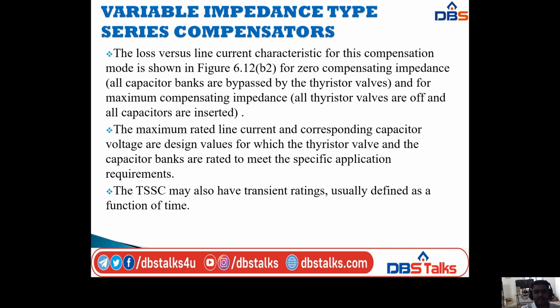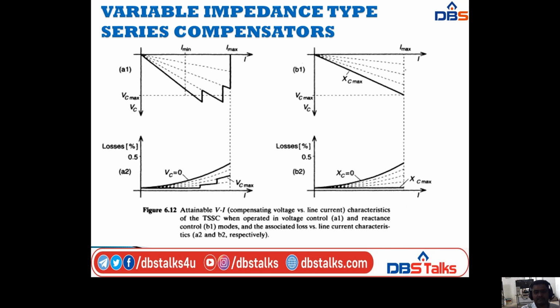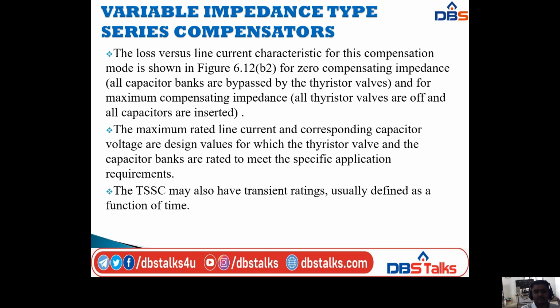Next I am discussing the last diagram of the VA characteristics and losses versus line current characteristics, that is B2. The loss versus line current characteristics for this compensation mode is shown in the figure. For zero compensating impedance, all capacitor banks are bypassed by the thyristor valves, and for maximum compensating impedance, all thyristor valves are off and all capacitors are inserted.